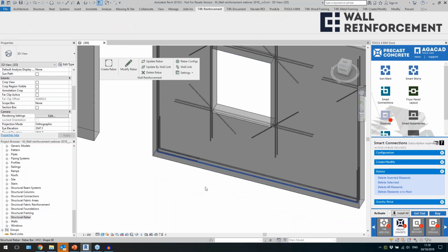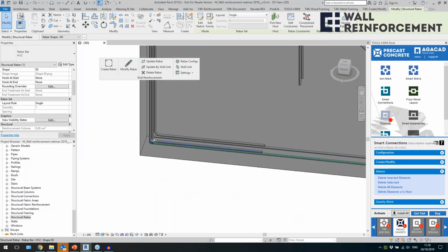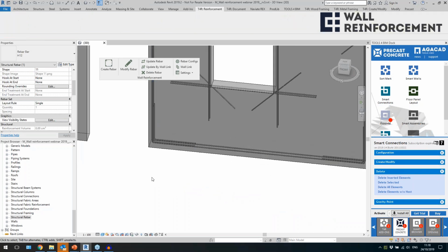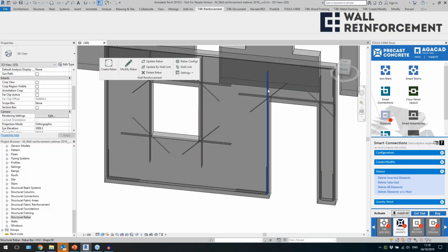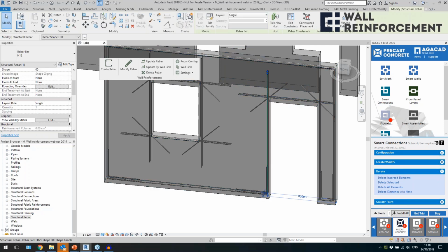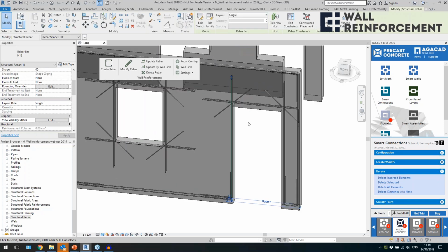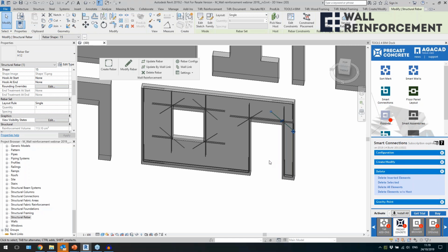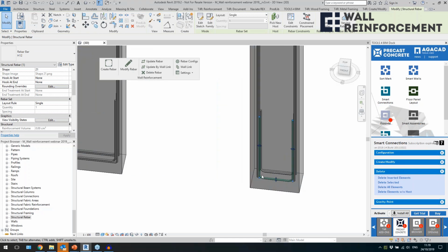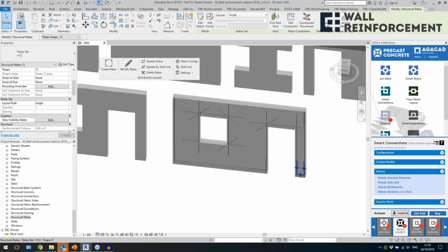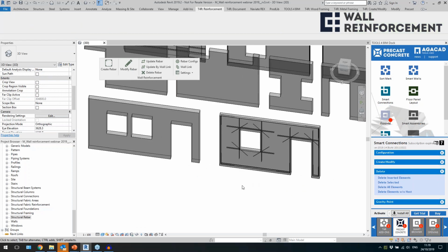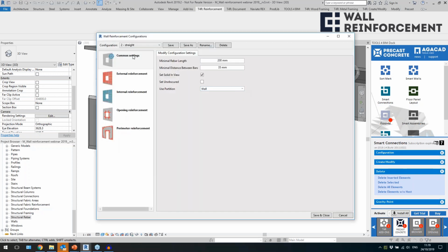So as I said, the perimeter bars: you have straight bars, you have these L-shaped bars in the corners, as well as these anchoring distances from the edge of the wall to the end of the bar. Then we have diagonal elements at the perimeter corners, and in this kind of situation it will bend like this. So that kind of stuff, right?